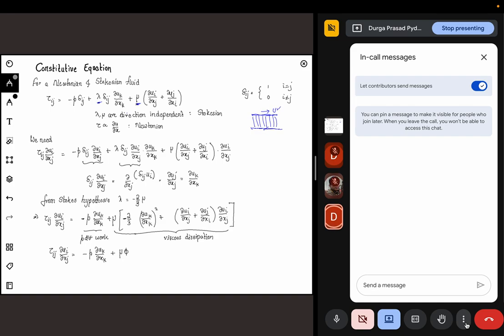But the thing that I can measure here is only the velocity. Let's say I can measure the force in a different way. If I can get the force directly, I can put some sensor here and get the stress directly. Or if I put a strain sensor or something here, I can get the stress. The question now is, how are the stress and strain related? In solids, we know that tau is proportional to strain, and we have some constant G or Y, depending on the type of load, to relate the strain with stress. Once we relate them, we'll be able to measure one of them and get the other quantity, right?